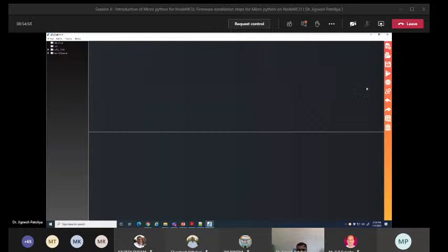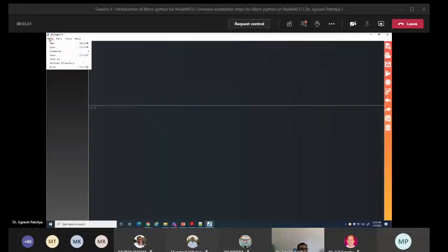And again, once you click on Tools, Serial, COM4, this will pop up. But here version 1.12; in the previous case it is version 1.13 or whatever latest version is available. But the only drawback is that if the net is not there, and you want to deploy or flash this MicroPython firmware inside your NodeMCU, we have to explore this user option. Now to check whether this board is in working condition or not, File,